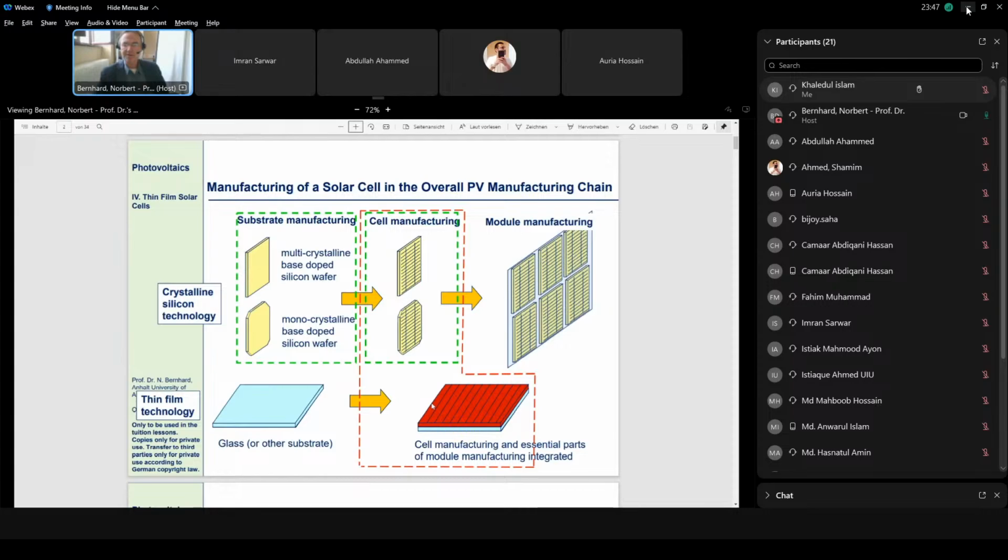And one should also emphasize, which unfortunately is not resolved here, that if you look at such a module at a distance of 2 meters or so, you see these already mentioned stripes. This stripe structure usually can be identified, and this is a clear sign that these are thin film modules.